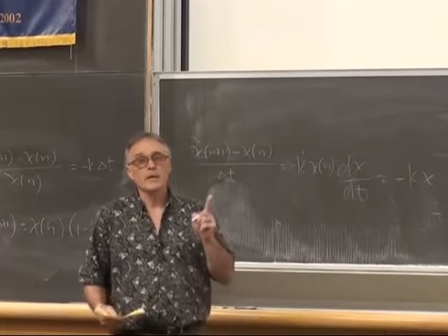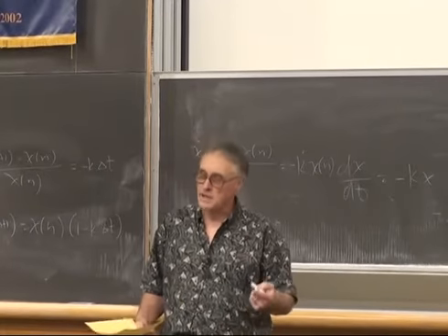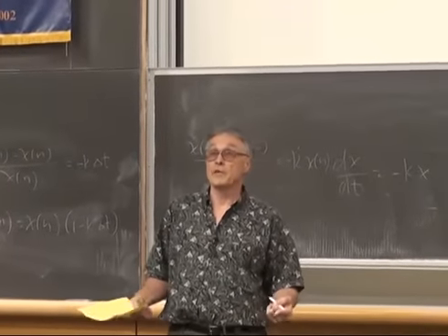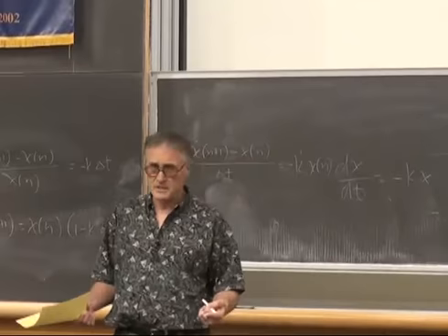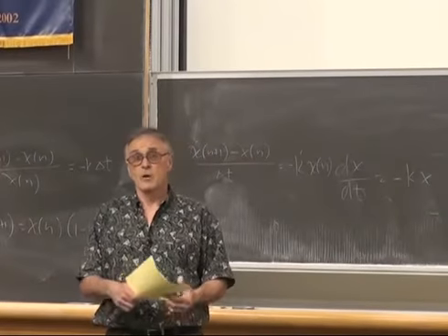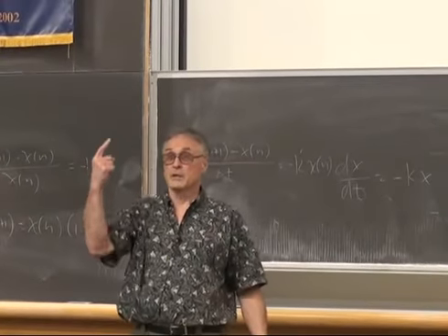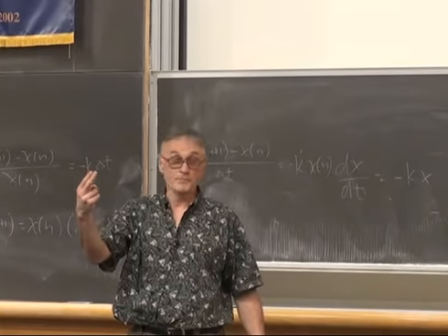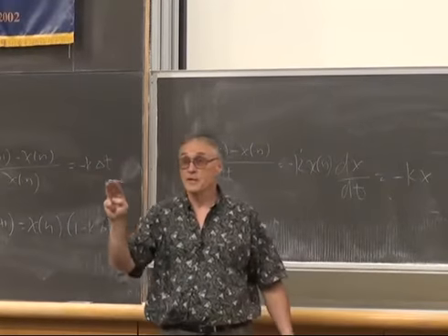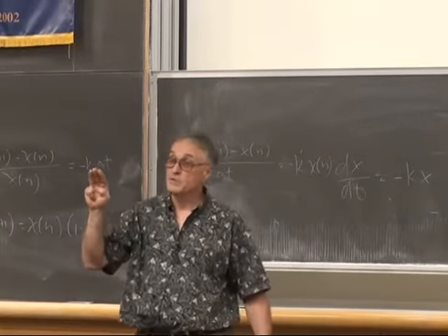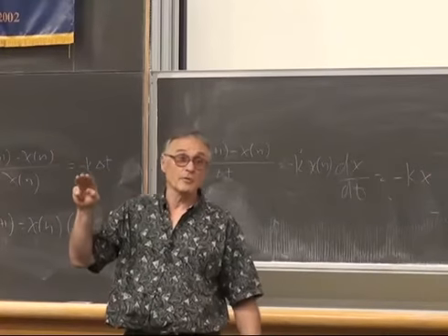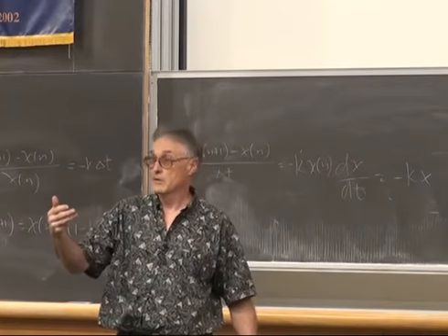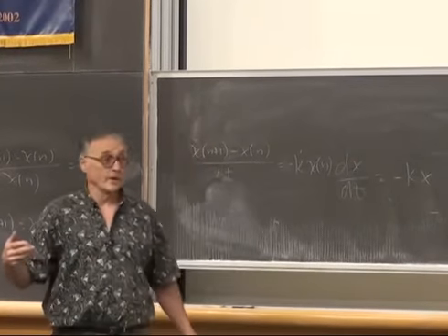So for every time step through the simulation or through the note generation at some constant synthesis frequency, we're going to update an exponential for the rise time. We're going to update an exponential for the fall time. We're going to multiply them together, and we're going to use that to set the amplitude of a sine wave or the amplitude of an FM wave.